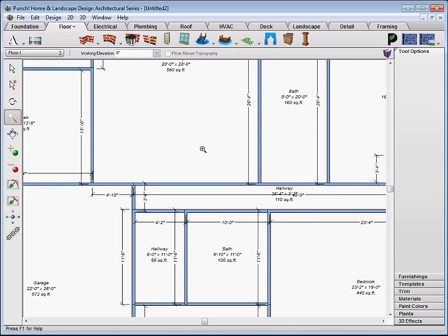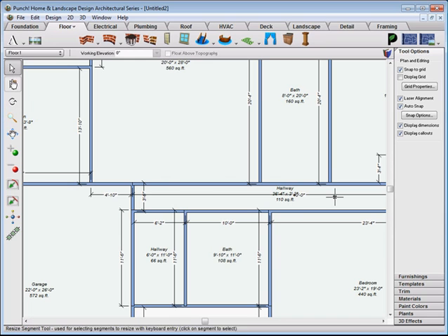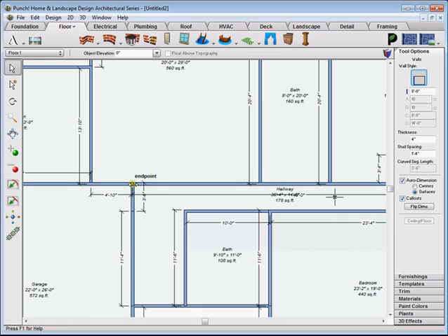Rooms are defined by enclosed perimeters. If I delete this wall, you'll see that one hallway becomes connected with the next. I also can move the corner of this wall going into the living room. When I release it, notice now that all of the hallways and that room are all selected as a single room. That means all of the estimating for that room would include the hallways.